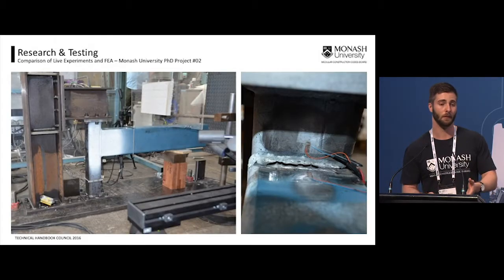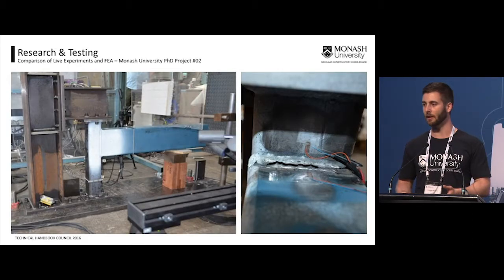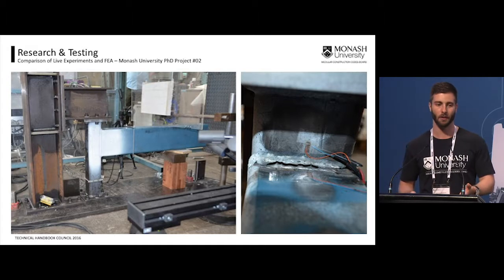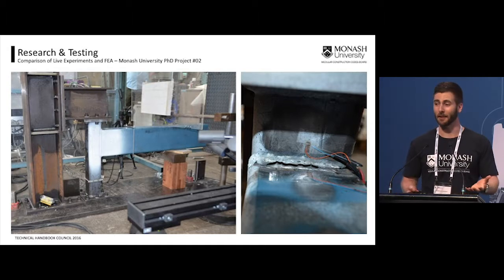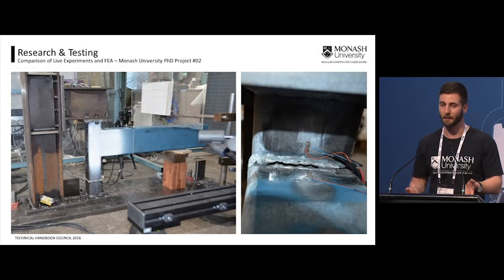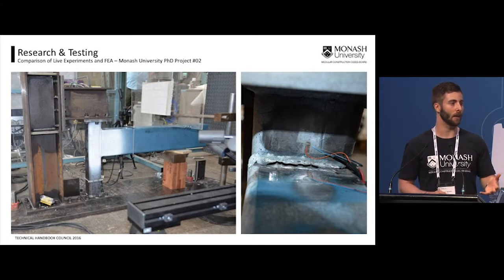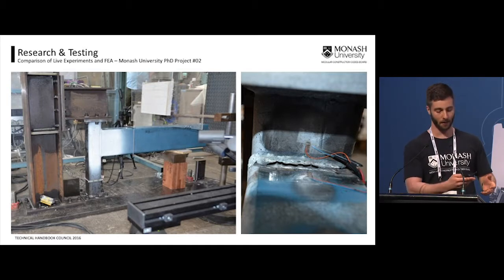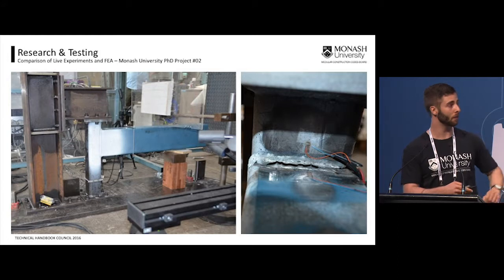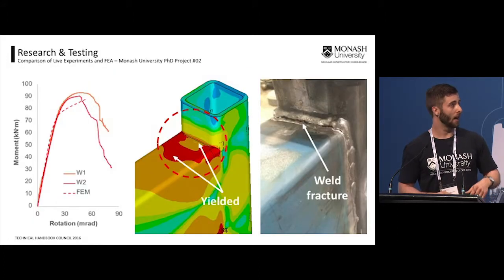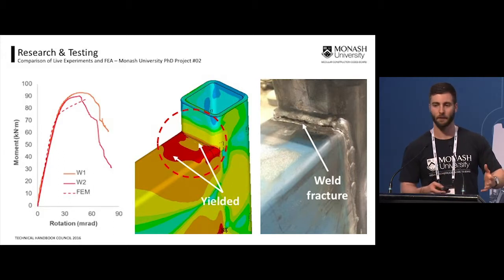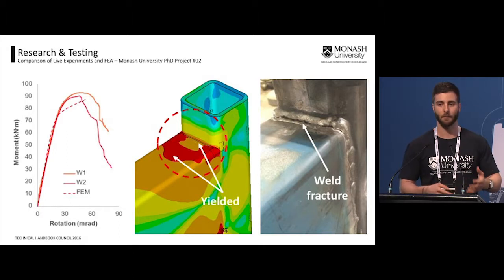And also we conducted some physical testing. So connections in modular design are incredibly important because at the end of the day, all these modules are being connected together. So to verify some of our connection recommendations, we've done physical testing here. Here's some various steel connections. And then we're comparing those to finite element analysis and showing that we have the same failure patterns, the same failure locations, and using that information to better inform the guidelines.